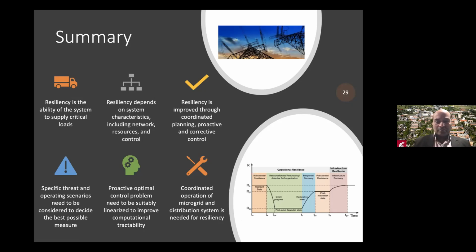And of course, with the microgrid, we cannot create a microgrid on the fly, so it has to be pre-planned and with certain flexibility, and that flexibility needs to be used to enable the resiliency when these extreme events happen. And we need to keep in mind the value of the dollar amount that we put, enabling it in normal operation, which is a blue sky day, and also in the black sky day, which is a critical operation.